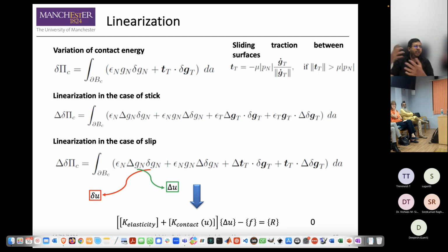So we did hundreds of simulations with different microstructures, different distributions and different particle sizes, to see what is the variability of the size that would separate out once the crack grows through this kind of microstructure. Now there were a lot of questionable assumptions put in there. I'll be very honest, because crack growth in rubber itself is another completely different PhD in a way, just to look at why the crack is separating out.